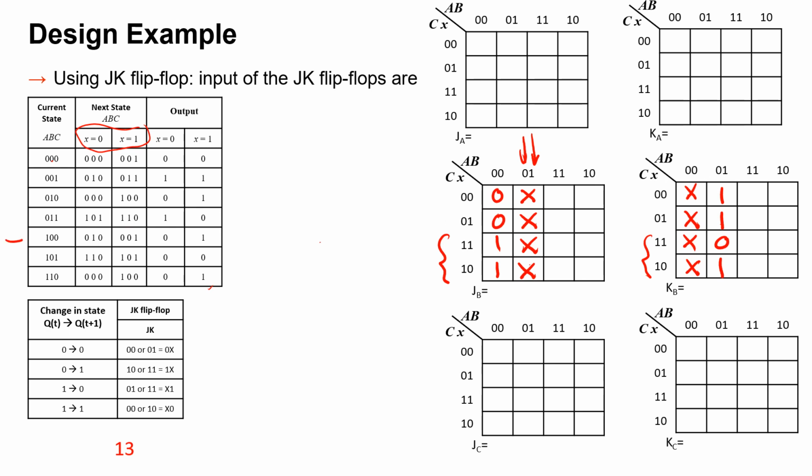The other row, this one. Well, we are not talking about output. We have done that already. Will be 1, 0. This one, A is 1, B is 1, C 0, 0. X will be 0 and 1. Two cases. And we are talking about transition on B, right? We have two transitions. If X is equal to 0, we have B transition from 0 to 1.